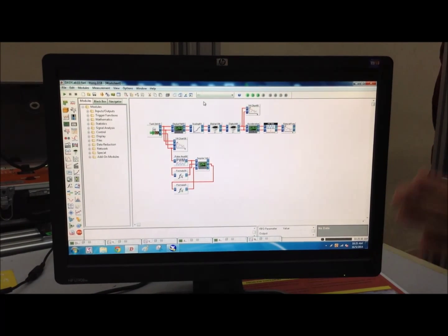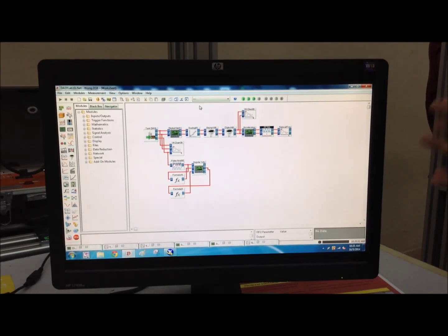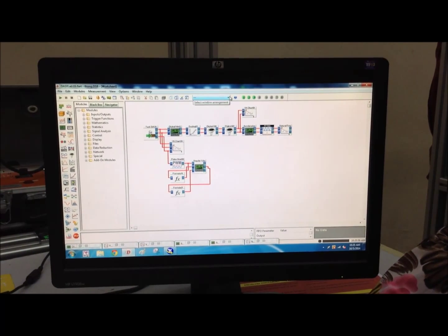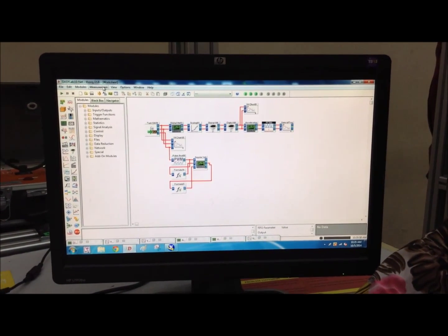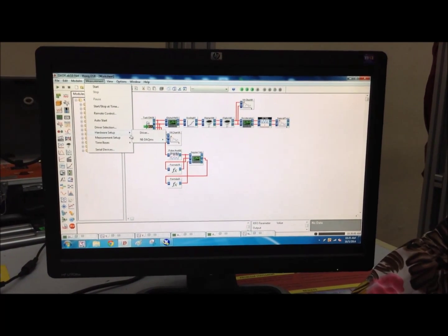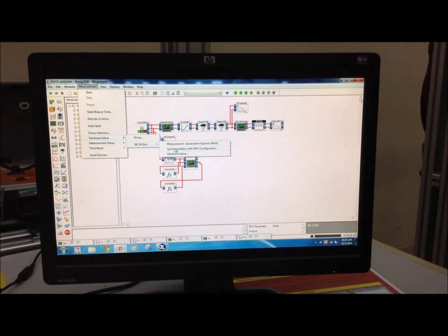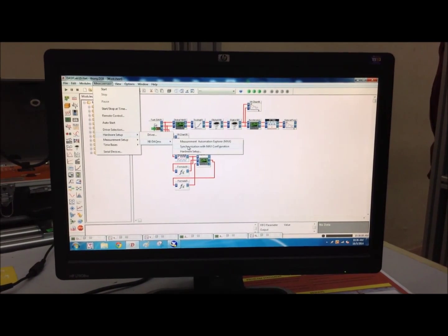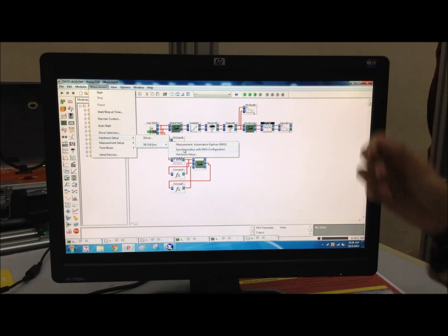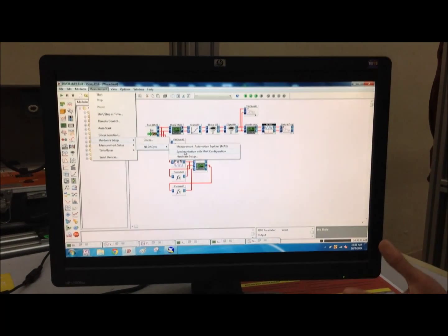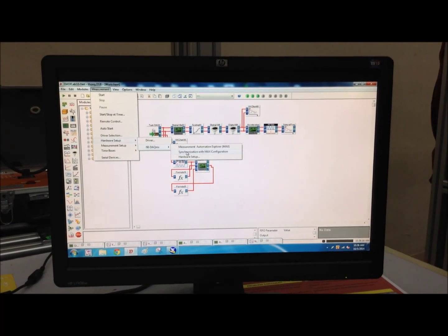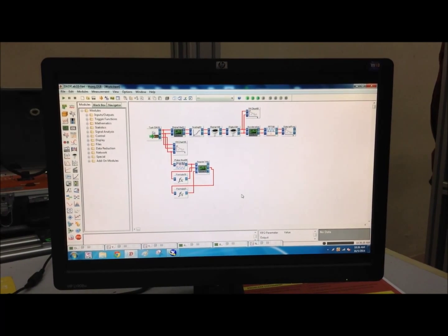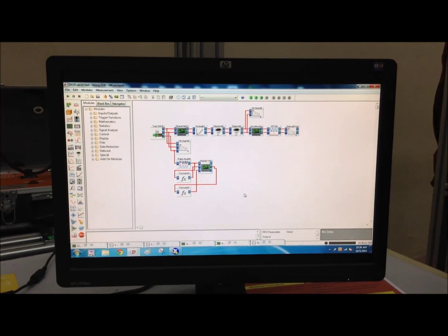After finishing the setup connection, click measurement at the toolbar, choose the hardware, set up NI DAQ, then synchronize it, and finally click run and start to record the readings. Tune the motor speed to the state of maximum beam deflection, record the frequency, and tune the speed to the state of minimum beam deflection, record the frequency, and DEWESoft is run to get other readings.